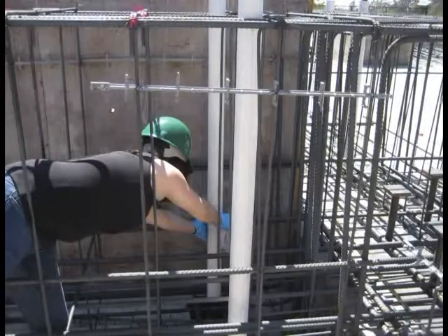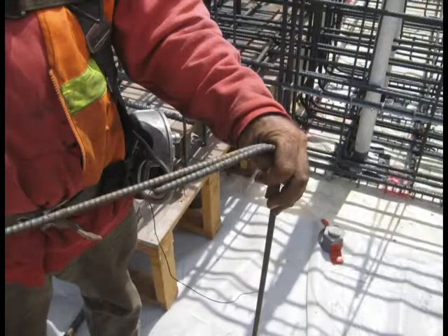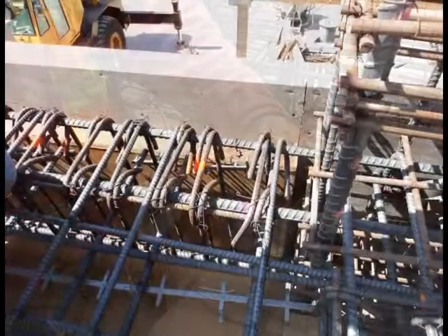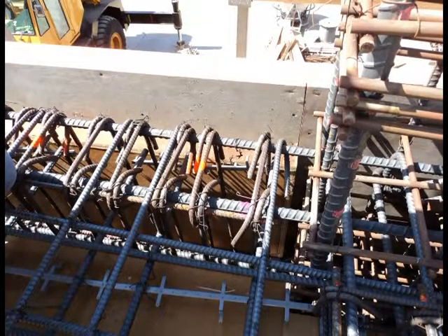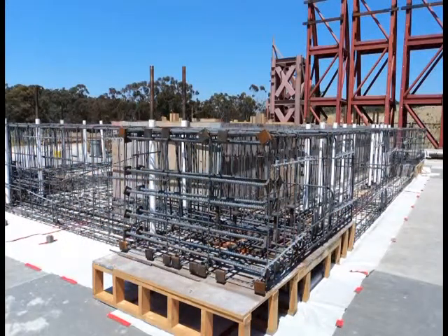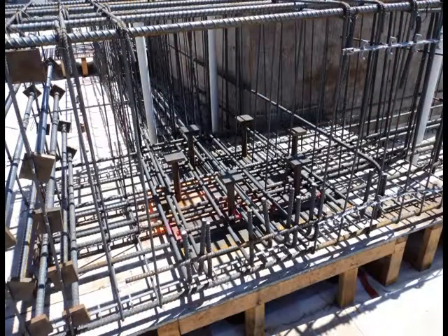Vertical longitudinal bars provide the concrete with increased tensile resistance to axial loads or flexural loads, which are due to out-of-plane bending. Transverse hoops or spirals provide confinement of the concrete core, help prevent buckling of the longitudinal reinforcement, and also provide shear strength to the column. Rebar cages, in general, also control shrinkage in the concrete, which will be induced due to internal temperature fluctuations in a concrete member. Therefore, the reinforcing cage can delay the onset of cracks in the concrete.